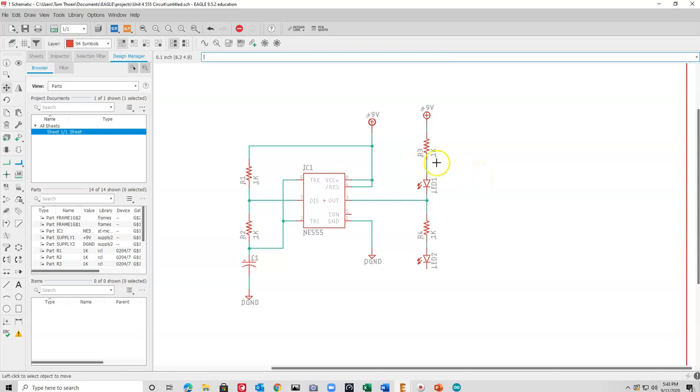Okay, so our schematic is pretty much done here. Let me look it over. So far, everything looks correct. But we also have the battery. Now, people will try to add a battery symbol to the schematic, but in reality, oops, oh, did you catch that? I left something off here. We're going to copy a ground symbol from here over to here. That was my bad. We would have seen that when we ran the ERC. Okay, where was I? Oh, the battery.